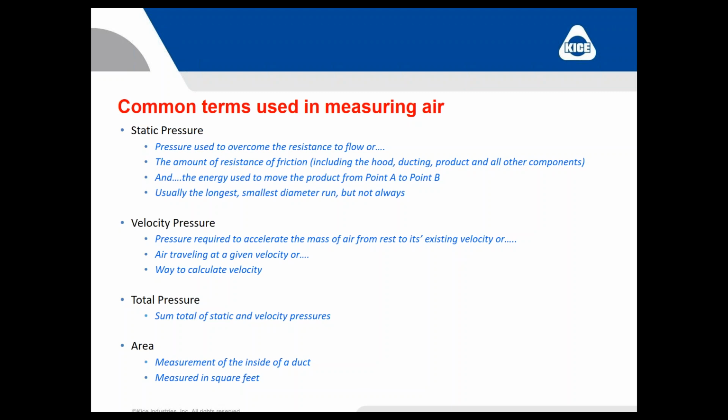So if you're doing a dust collection system, we like to look at the whole layout and work backwards until we find that highest static system, and that's what we base our fan selection on.